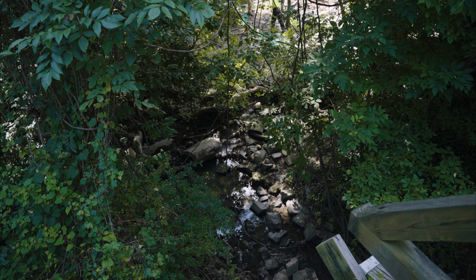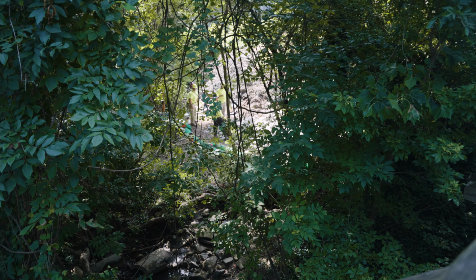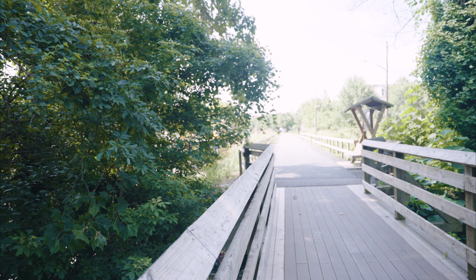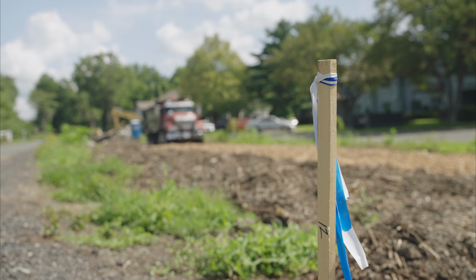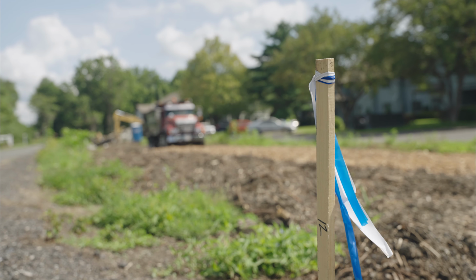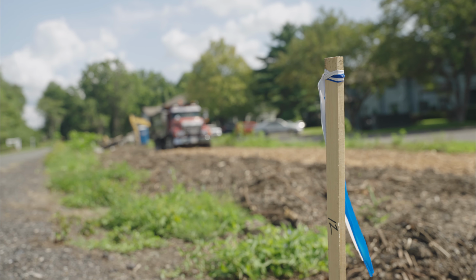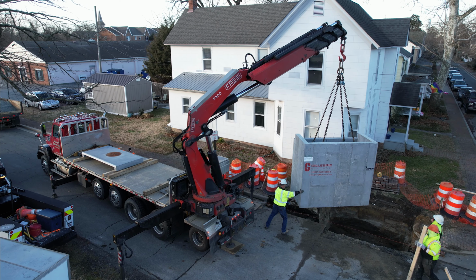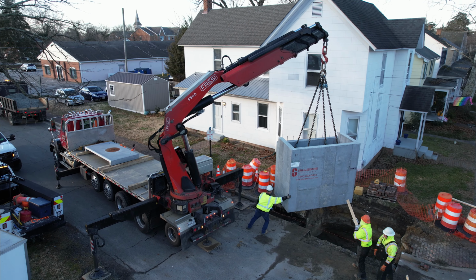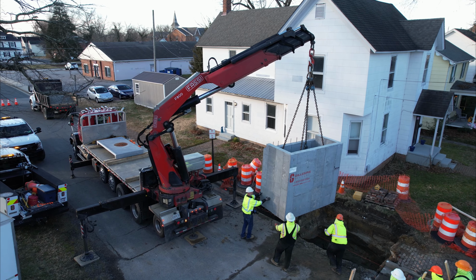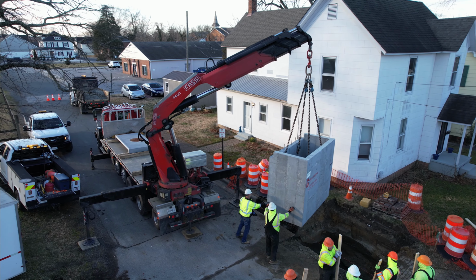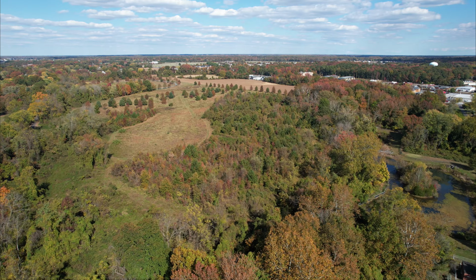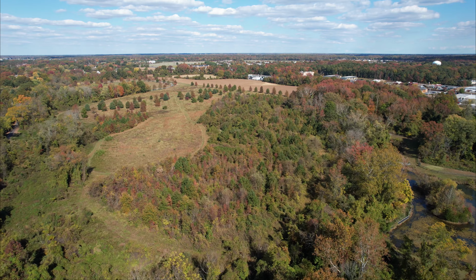As the first step in the design process, an initial survey was performed to map existing topography and impervious surface, and the location of all existing underground infrastructure, including water lines, sewer lines, gas lines, and electric and fiber conduit. With these existing conditions and constraints identified, the design progressed through a series of design milestones, which were identified as 30%, 60%, and 95% designs.